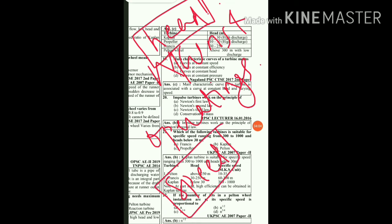So irrespective of the load, whenever we have to plot operating characteristic curves, we need to maintain a constant speed, and for main characteristic curves we have to maintain the head constant.